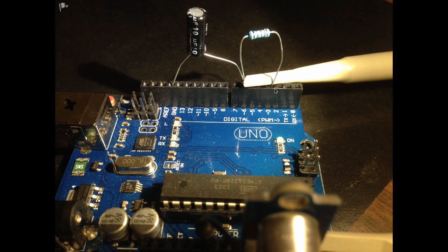And then we connect the pulse width modulated signal that's coming from pin 3 through the resistor into pin 6. And so these two here make a filter that then produces a constant DC voltage on pin 6, whose magnitude is proportional to the width of the pulse that is coming out of pin 3.